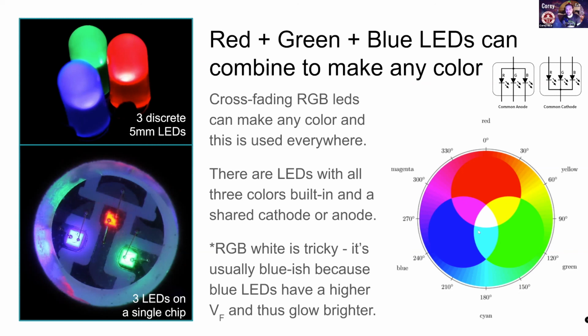I've actually bought LEDs in the past that have 4 dies on them, a red, a green, a blue, and a dedicated white chip, because it saves some power to only have one on instead of three. And that dedicated white chip can be tuned to just the right pitch of white. If you're thinking about how many Kelvin it is for a warm white or a cool white light, that's something that's a little bit tricky. You can dial it in with RGB. You just have to put in some effort, and it changes a bit chip to chip sometimes, like category or batch of chip to chip.